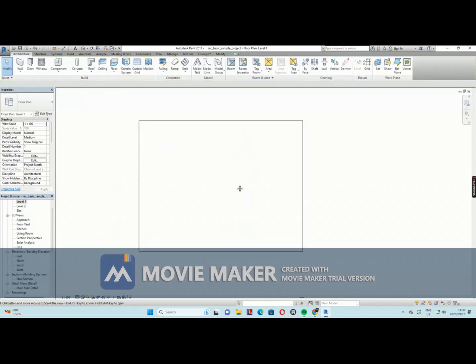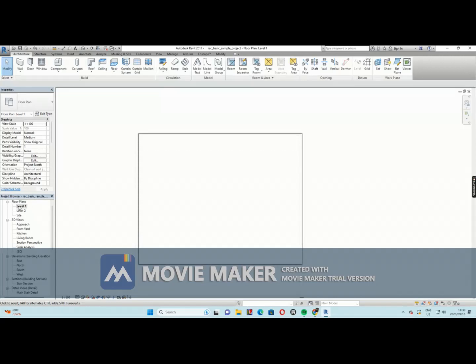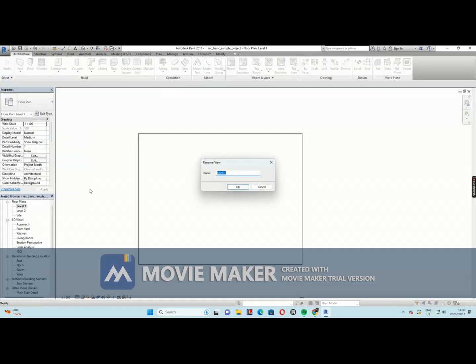So what we do now, we are starting a new project. Before you start a new project, you must go and check your levels. Yes, we are in level 1. For me, let me call it, I can rename this one to ground level. Okay?